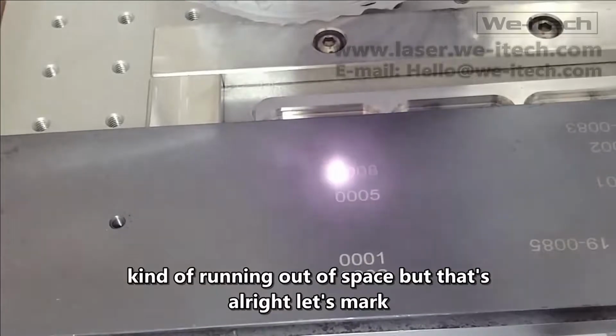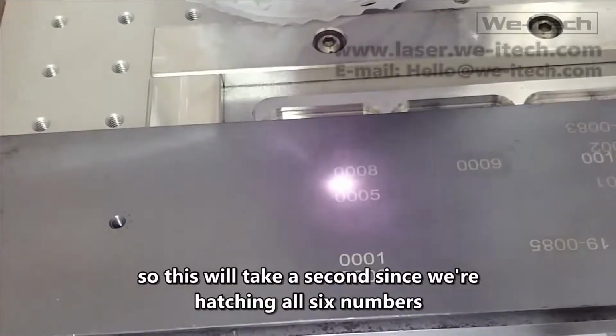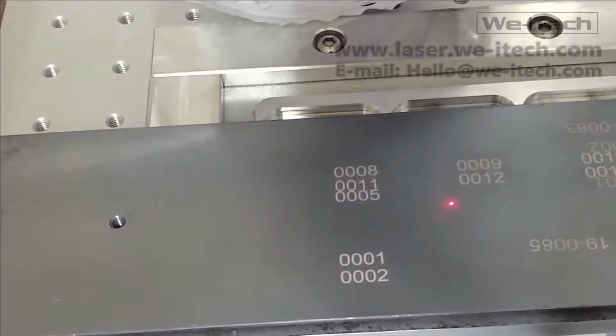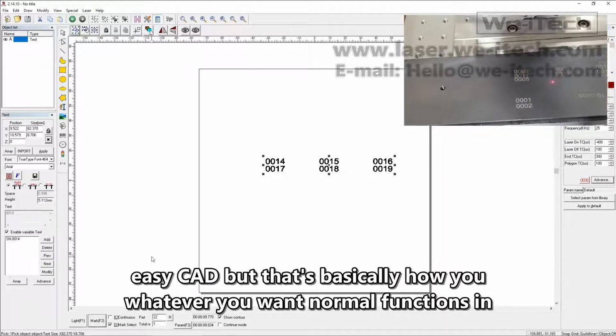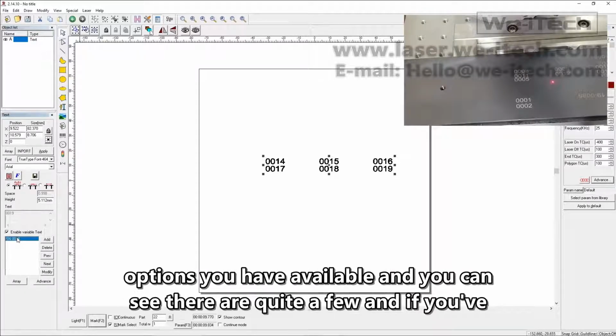Let's mark. So this will take a second since we're hatching all 6 numbers. So you can see that's how it showed up, and you can change the spacing, do whatever you want. Normal functions in EzCAD, but that's basically how you set up a serial number and the different options you have available. And you can see there are quite a few.